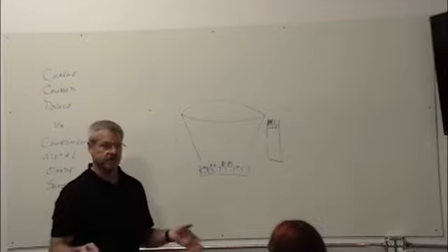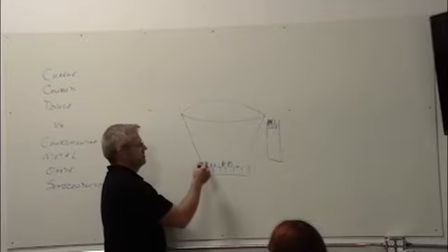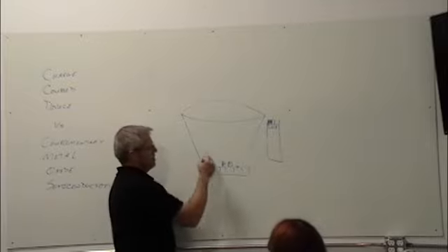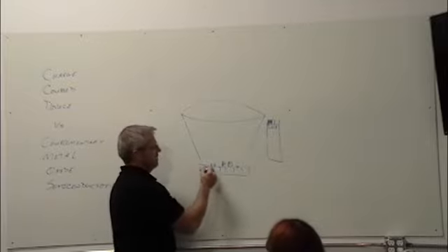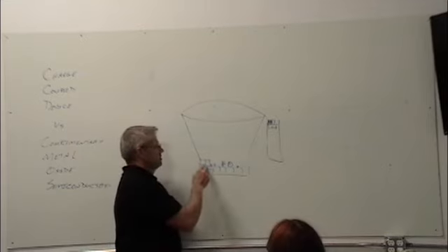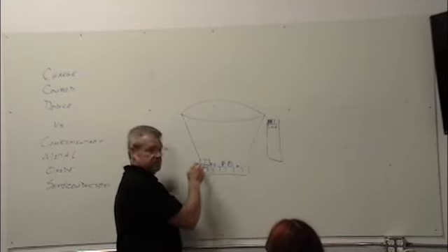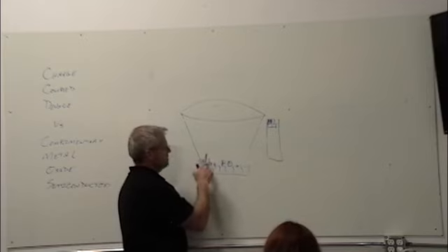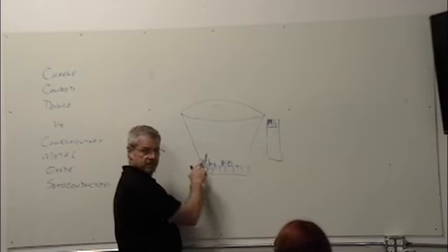Now you can intentionally oversample, and when you do, 1 pixel out there lands here, and maybe I don't report back to the image this 1 big pixel. But now I can play signal processing games in here, and I can say, well, that edge, this pixel is darker than this pixel by 20%.